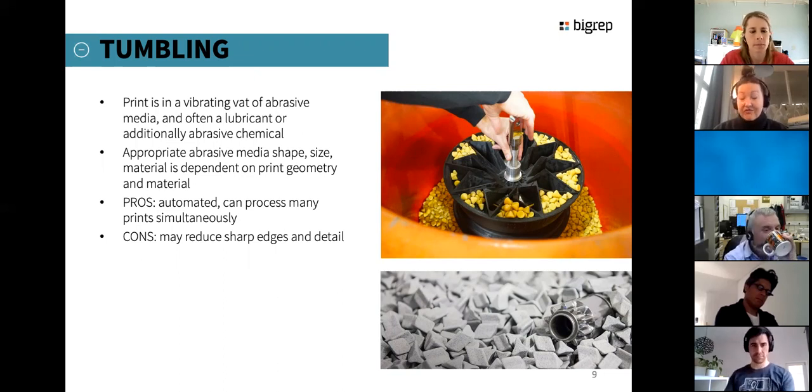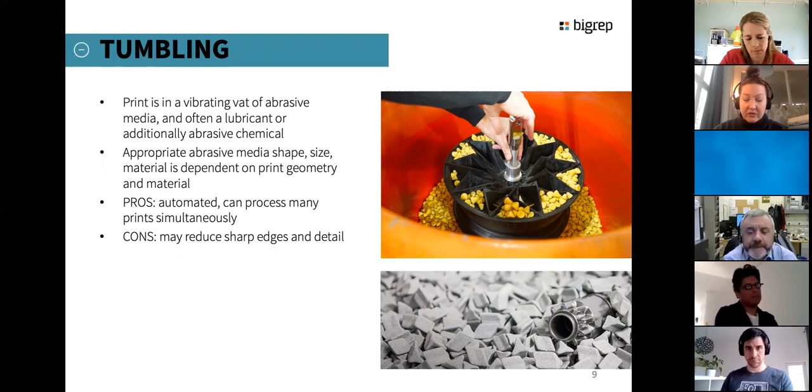The easiest by far is the PLA ultralight, which is a foam material. It's a PLA foam that when it's printed and heats in the extruder, it foams up, so part of it is air bubbles. If you're looking for something really easy to sand, maybe for a show piece that doesn't need other functional properties, that one's super easy. You could do it by hand really easily. So that's maybe an option if you want something you can sand super easily.